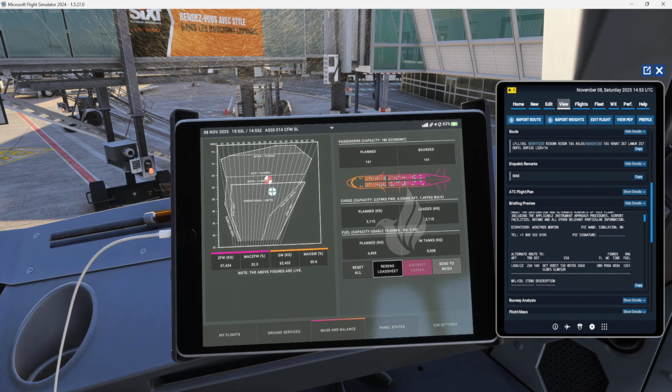So the basic empty mass, if we add the crew and standard equipment, we are going to get dry operating mass, because zero fuel mass you cannot calculate directly. The dispatcher will give us a paper, but you need to do your calculation. As a pilot, yes, for us it is easy to calculate from the mass and balance EFB, but things do not work like this.